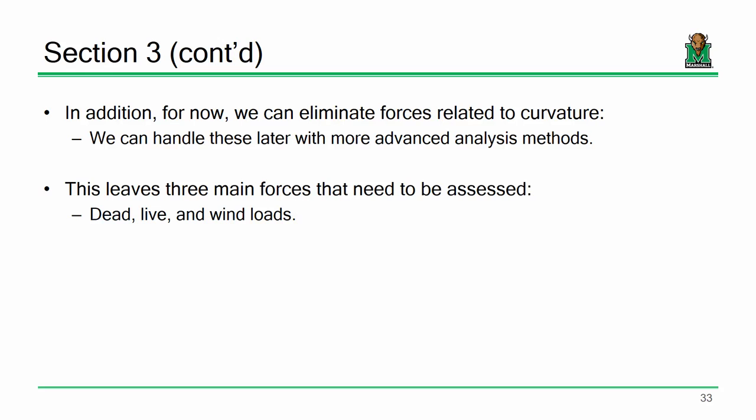So we really only need to worry about 3 main force effects right now: dead load, live load, and wind loads. And some of you could go, wait a minute, it's West Virginia. What's going on with that snow? True, yeah, bridges see snow. But in our load model, we incorporate a 64 pound per square foot load anyways for vehicular traffic.